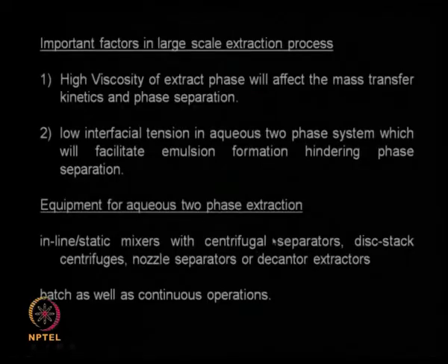This type of static mixers have been considered. Once you mix them, you use centrifugal separators, different types of centrifuges. We talked about different types of centrifuges. You can use disc stack centrifuge, you can use nozzle separators or decanter extractors and so on.